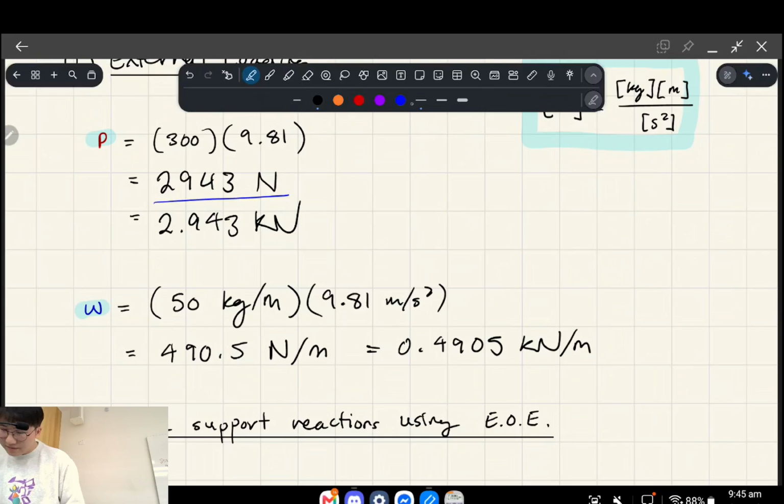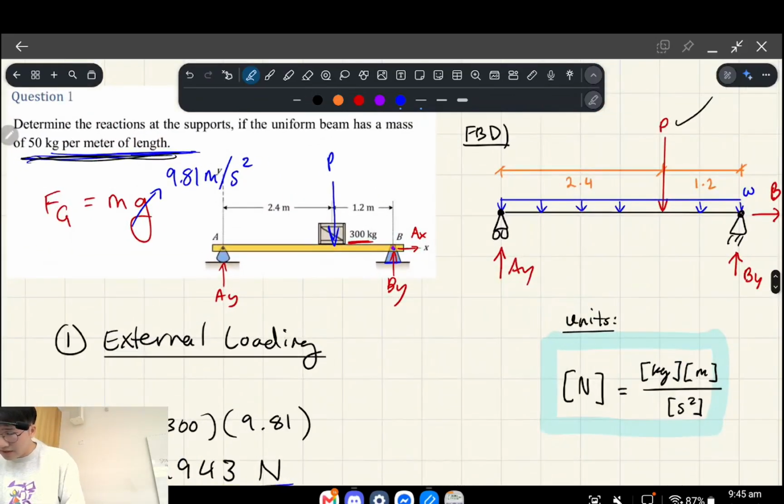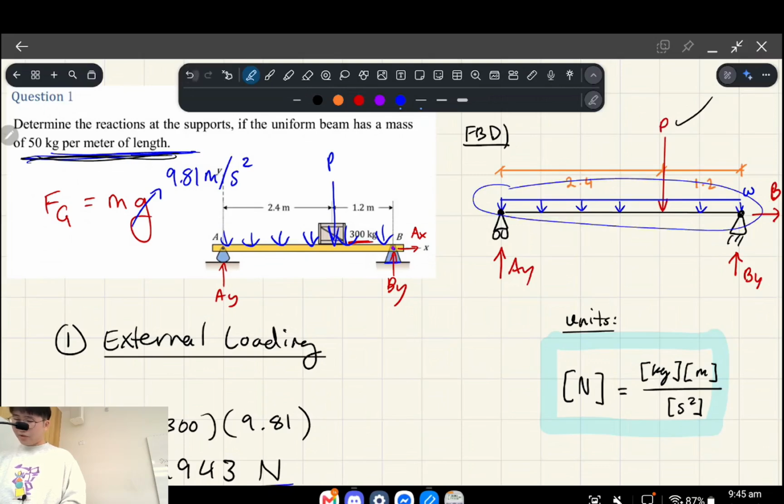Right? And this gives us something called a distributed load. We'll be talking about this a bit more next week. But this is a distributed load. The idea is that instead of the force being at a single point, like the middle, it's essentially spread out over the whole beam, like this, because it's the self-weight, okay? And we represent it on pen and paper like so, like this rectangular shape pointing downwards, okay?